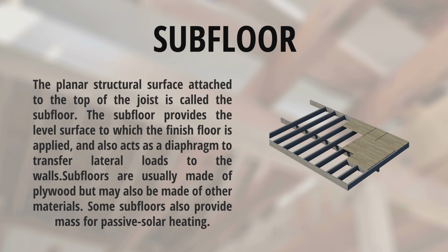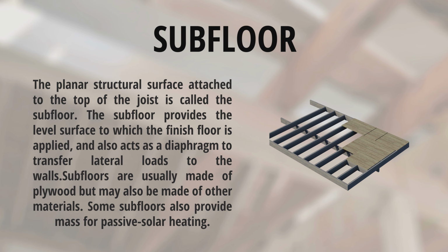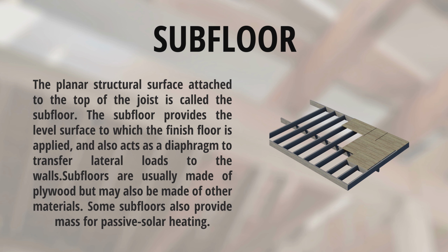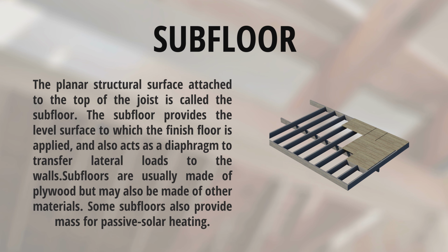Joist or girder. Edge blocking is required if subfloor panels are not tongue and groove and underlayment is not used. Surface grain of plywood subfloor panels is perpendicular to supports. Stagger end joints of the subfloor panels. Offset joints of subfloor and underlayment panels.